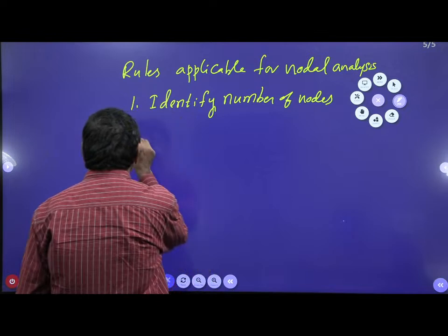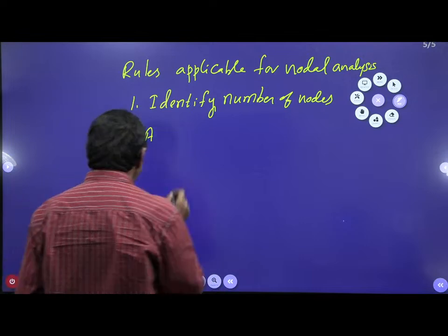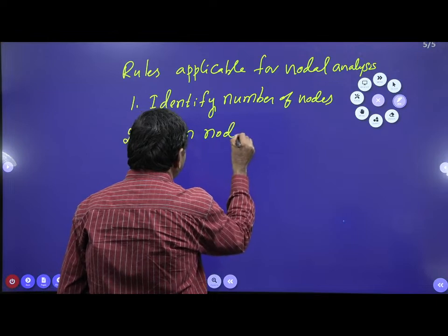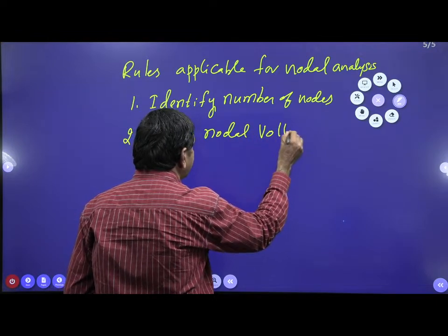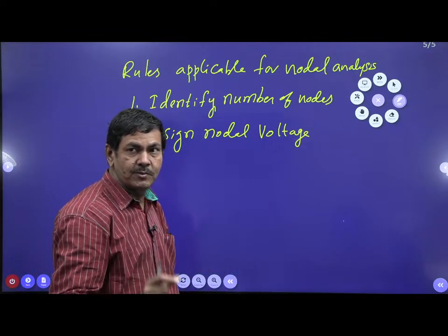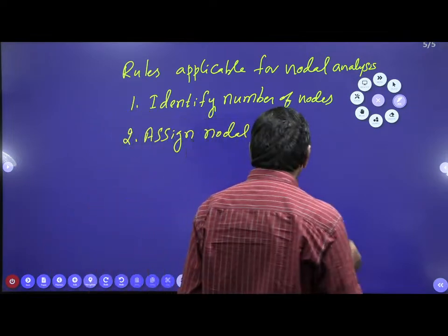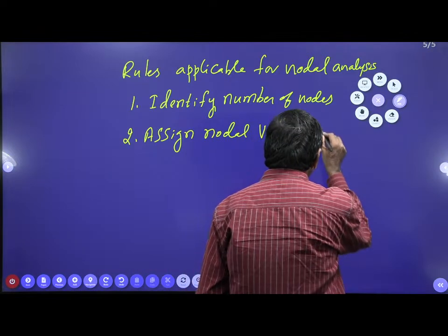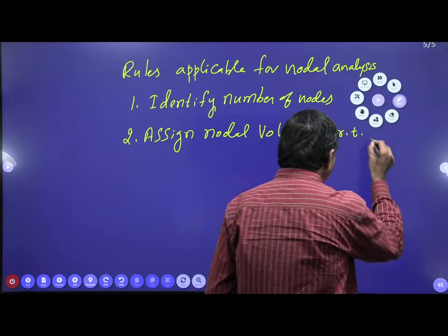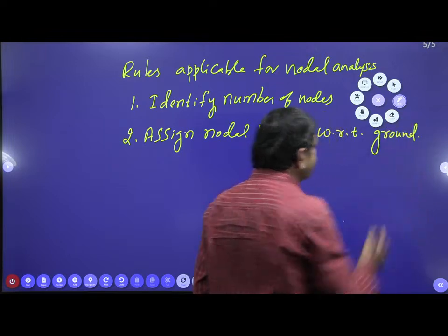Assign nodal voltage. The node you have taken has some voltage with respect to the reference. Reference means ground. So the nodal voltage is with respect to the ground. That point is very important.